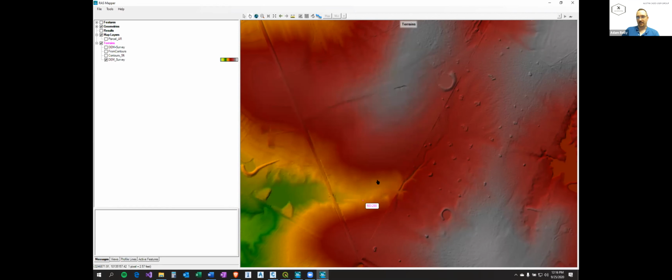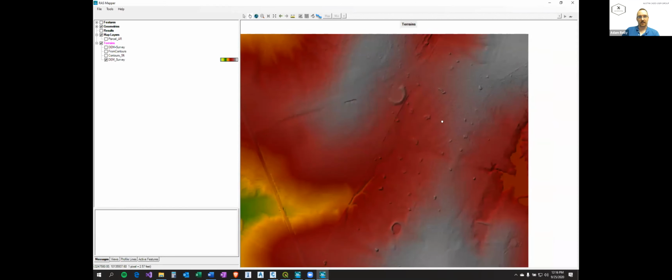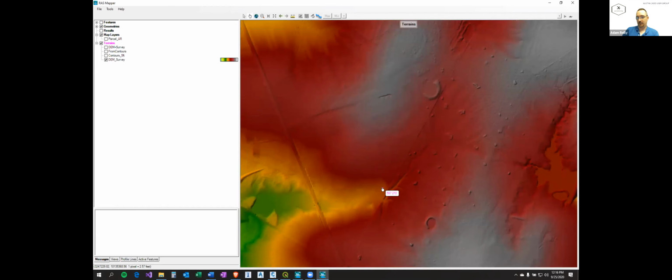As long as you have that, you should be fine to project any data that you bring in, to make sure it's all correlated and on the same coordinate system. My question was, when you're bringing in DEMs and survey data that have different projections, like anything we get from TNRIS is in UTM, is HEC-RAS projecting on the fly to that coordinate system you just set?